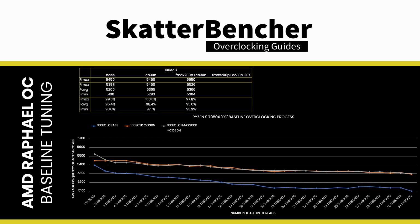The programmed Fmax is 5650 MHz, which means our effective Fmax is at 97.8%. The average frequency is 5366 MHz, 1 MHz over our curve optimized setting, and the minimum frequency is 5304 MHz, which is 9 MHz over our curve optimized setting. Unfortunately, the scalar adjustment made no difference in maximum, average, or minimum frequency.